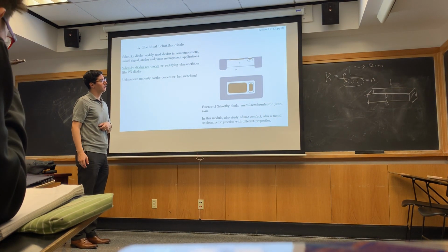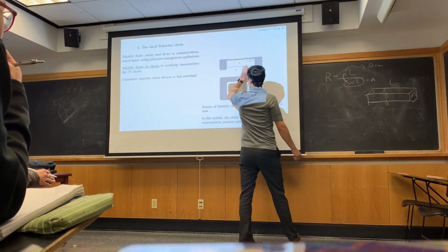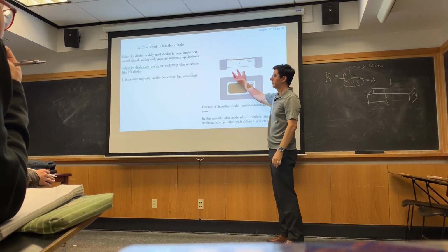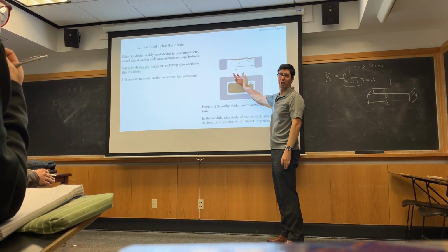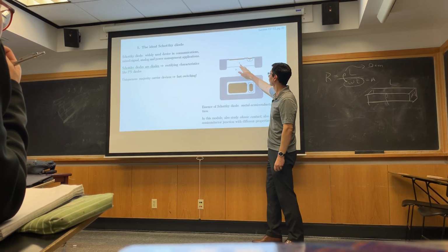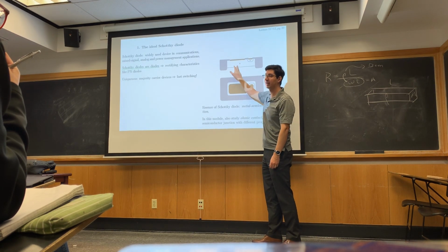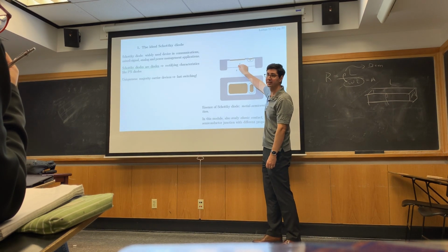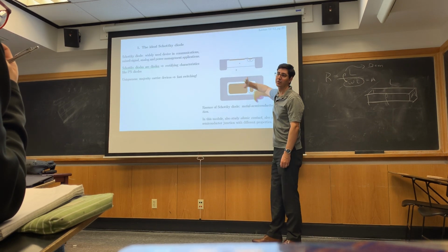Okay? So here, I hope this looks similar to the PN diode. This P region's not there to confuse you. It's just on a bulk wafer. It's always doped to something. And so the device of interest is just right here. It's this metal semiconductor junction. This is just a contact. This effectively is a contact to the backside here. And this P region here isolates this from other devices.